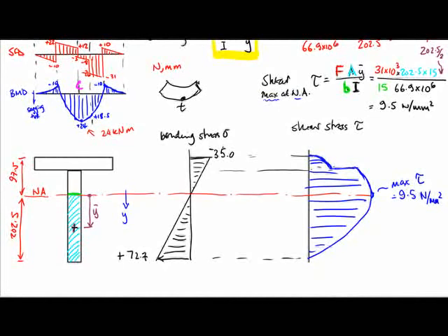And if we wanted to get the separate values, since it's not a straight line, we will have to go at various points, at various levels, to make a cut. So if we wanted the shear stress at this level, we would then have to make a cut here, and go back to the Ay-bar equation to get the values.